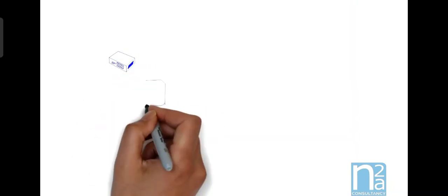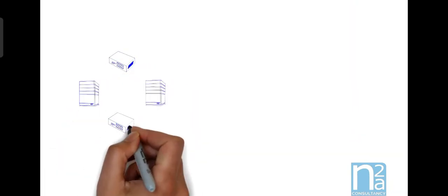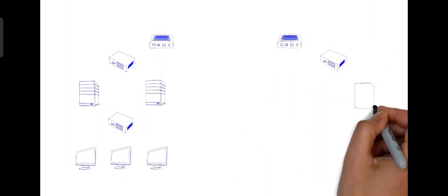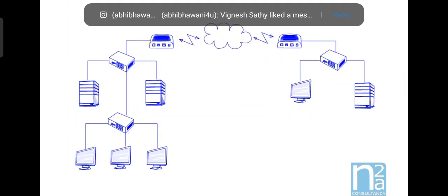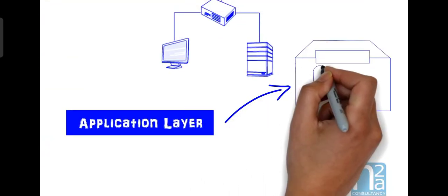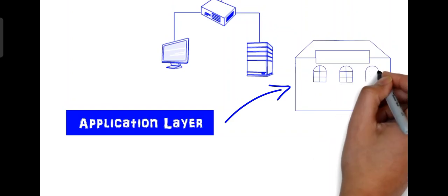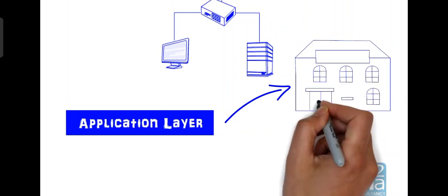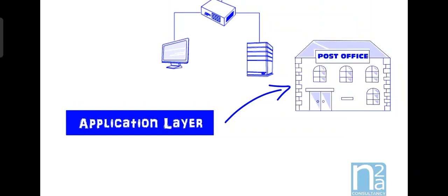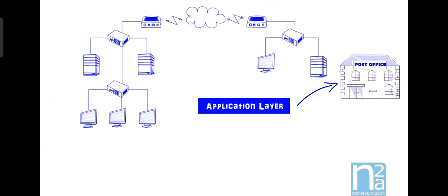Before talking about the communication protocols of IEC 61850, we should have a quick word about the Internet protocol structure. The Internet is based on 4 layers, meaning 4 independent levels of services to deliver the information. The top layer is the application layer. It uses simple commands to transfer data from one point to another. For example, the application World Wide Web, www, is used by all Internet browsers to access web page content.